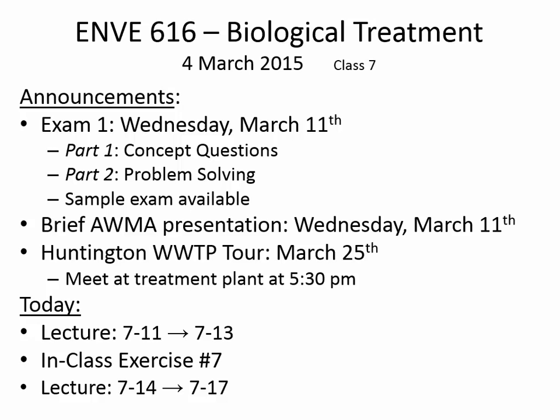Now some of the questions are going to come from the vocabulary words that I gave you at the beginning of slides for each chapter. Infiltration is one of those commonly used terms in wastewater treatment that I think you should be familiar with. Infiltration is from broken pipes. That's when groundwater seeps into the collection network. Sometimes infiltration and inflow are measured together because when water's flowing through the sewer, it may be hard to know what was infiltration and what is inflow, but they do have specific definitions.